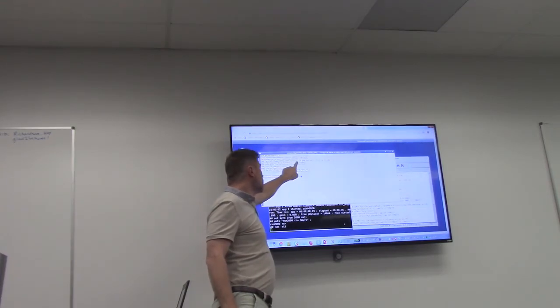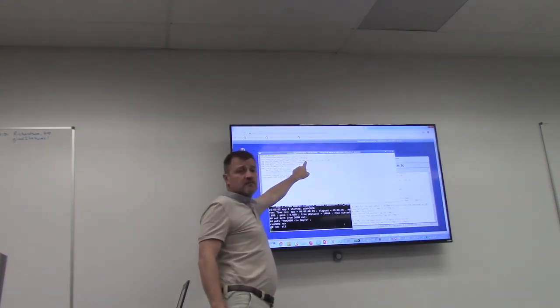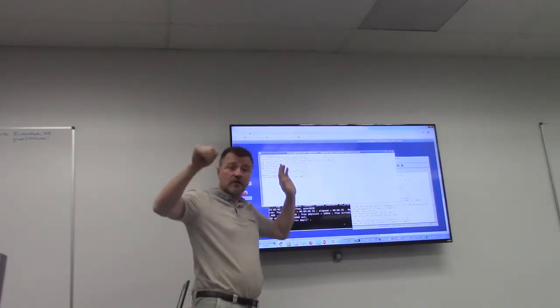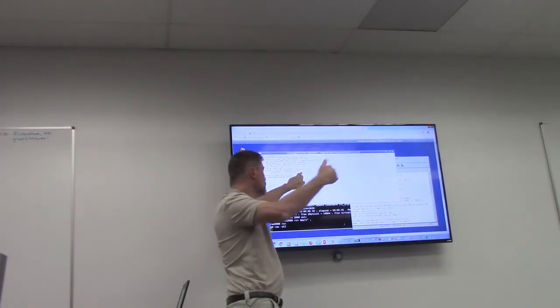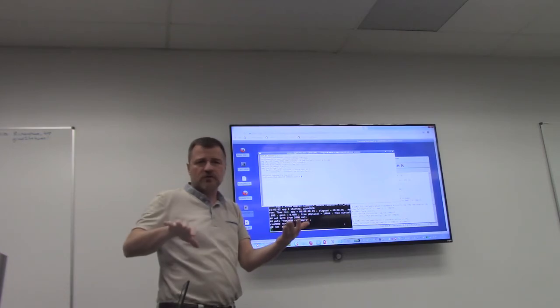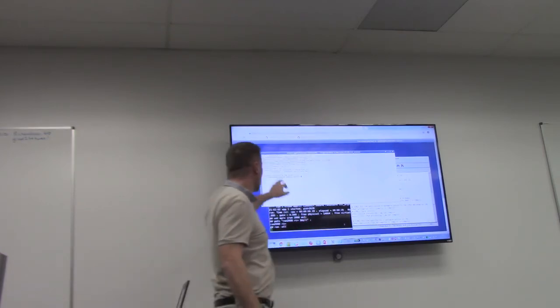It says no NVMe on the card. No RAM has been hooked up. There is RAM on the card, but we said we don't need the RAM because it's a hello world. We unselected the RAM. In the main menu, by selecting HLS hello world, in the background, we said we don't need the DRAM for this basic example.